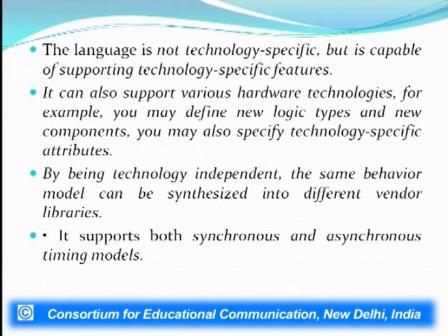There are different vendors which have their own libraries. For example, there is a UMC library, and then there is a TSMC library. These libraries have their own individual attributes, but VHDL, being technology independent, can be very well integrated into any of these libraries. Then it supports both synchronous and asynchronous timing models. So, all types of digital designing can very well be accommodated using VHDL.